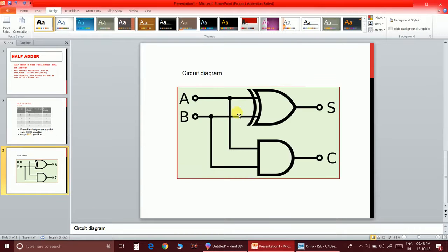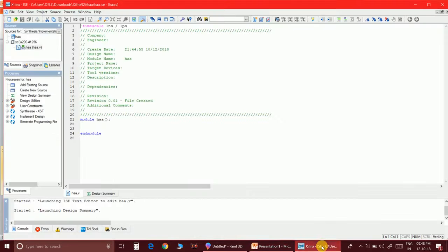Finally, from that we can write: if A and B are treated as two inputs for a half adder, and this can be treated as a whole block, then I can write the sum as an XOR gate and the carry as an AND gate. So with this basic idea, now let's get started to write the code. And you know that I declared inputs A comma B and the outputs as sum comma carry. So now inputs, I will zoom this.